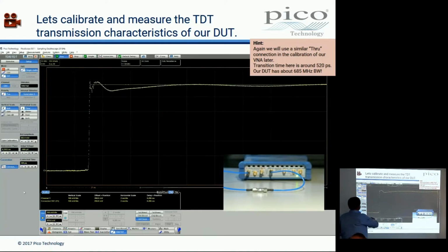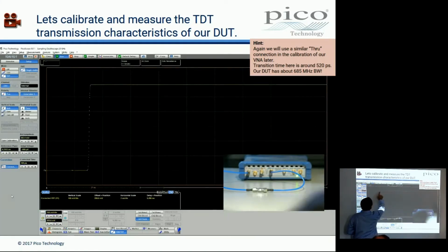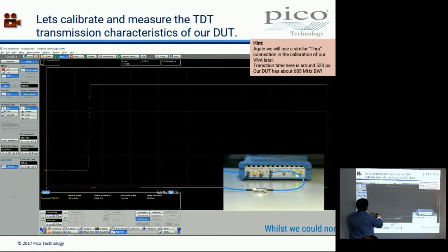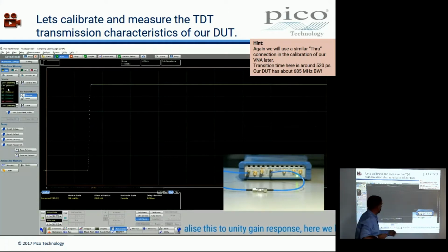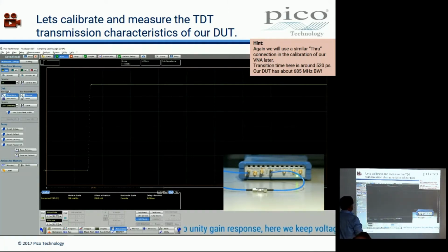Okay, now, if you can see the other yellow trace underneath, I'm going to turn this top one off in a minute. There you go. So it's now defined. That's going to be unity gain. This is naught gain. That's 1 gain. And this is an ideal edge shape here now. So we've now got an ideal pulse for our analysis of this network, this DUT that we don't know anything about.